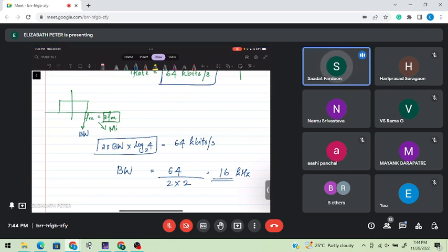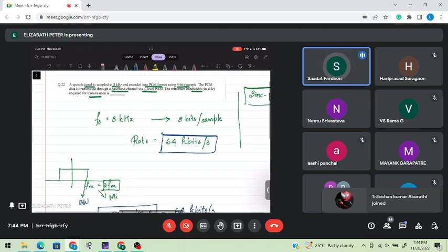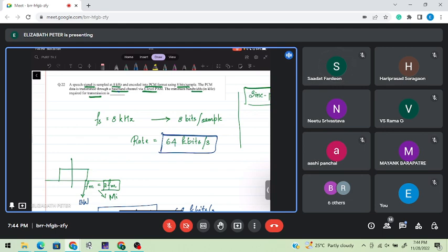So you're telling that the data rate is 64 kbps. Yes. And the data is being transmitted using 4 PAM symbols. Hence, what is the minimum bandwidth? Yeah. So baseband channel means there will be a pulse shaping associated. So the minimum bandwidth means the minimum bandwidth of the pulse shape that is used. That is actually what it meant.